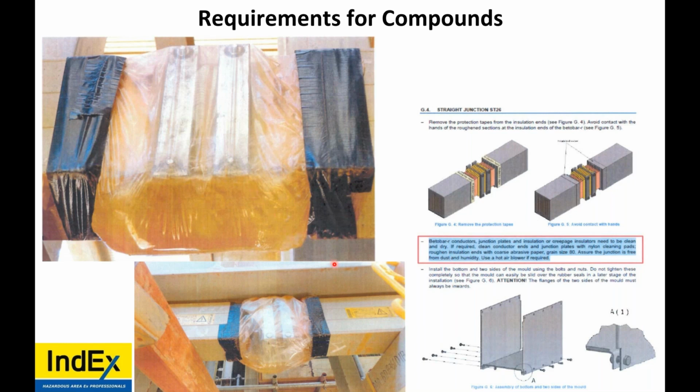This happens all the time, water ingress. Anybody that says that IP ratings or water ingress does not affect the explosion protection of EX equipment, look what's on the screen. Now, the problem is, what happened to the encapsulant? Did it absorb that water? Will this joint fail in the future?